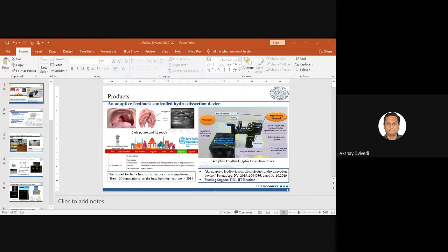Okay, this is a wonderful process. You were able to remove the passivation layer. Now what? So the thing here is, in this process, it was identified that whenever we work with discharges, these discharges are able to provide consistent results only up to a depth of 300 micrometer. In fact, for this process, it has been realized that up to 300 micrometer depth, in fact, I should use this range, 200 to 300 micrometer depth. The process works in discharge regime, wherein discharges basically create the entire kind of damage that is there.